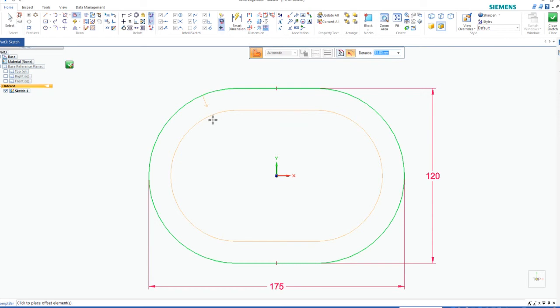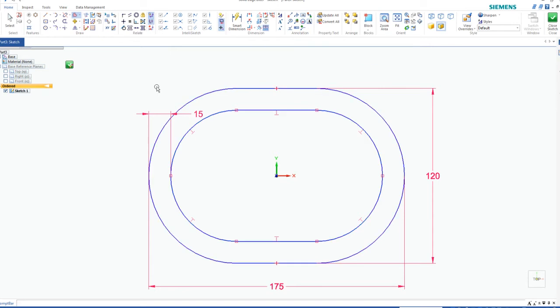Now the distance between the silhouette and the green edge is a total of 15. So if I left click and then I hit escape, I now have that projection. I don't have to worry about creating lines and arcs. It will do it for me automatically. So that's the beauty of offset. If you haven't played with it as often, I absolutely encourage you to try it when you can. All right, so we have the majority of what we need to start.